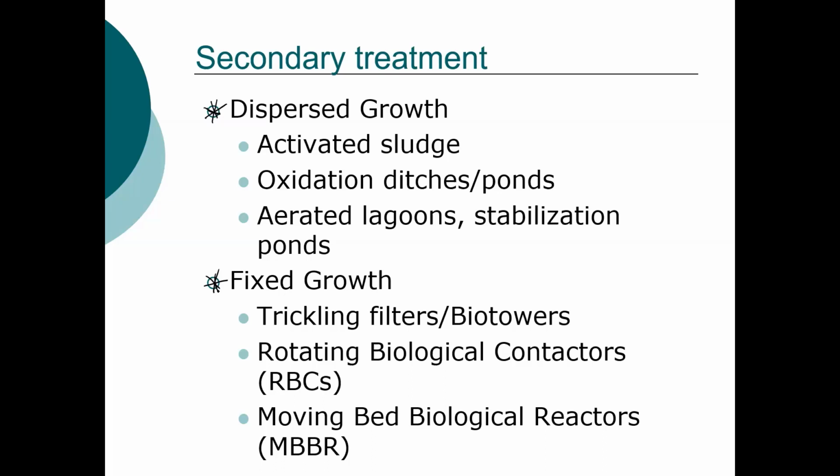So here we have some surface. On that surface, we have our microorganisms, and the water is flowing past the microorganisms, and as it contacts the microorganisms, they obtain all of the nutrients that they need in order to grow. So these include trickling filters, biotowers, rotating biological contactors, moving bed biological reactors.